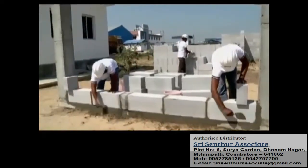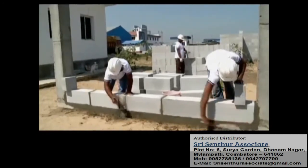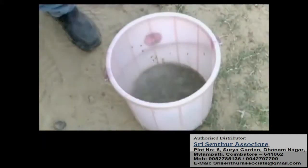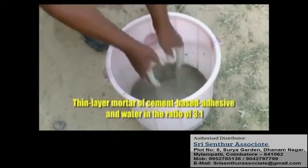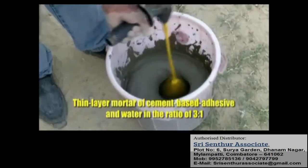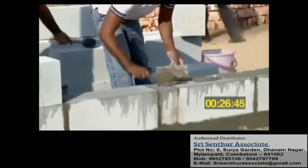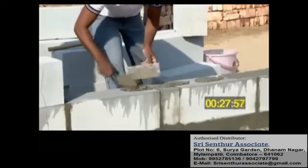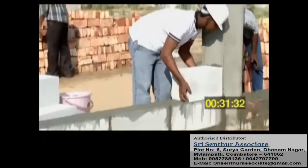After the base layer is complete, the thick mortar is not required anymore. Another distinctive advantage: a thin layer of mortar of cement-based adhesive and water in the ratio of 3:1 is prepared for building the rest of the wall. The thin layer mortar is then applied with a trowel to maintain a thickness of 3 mm and avoid wastage. As usual, the layers are erected after first laying the corner blocks.